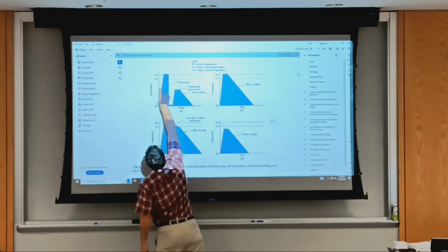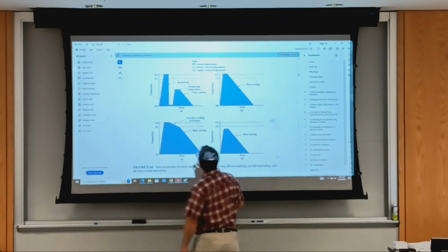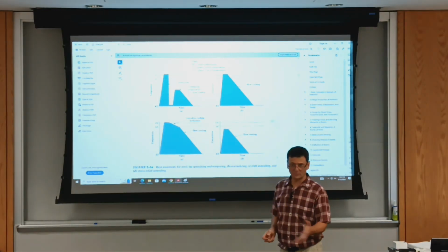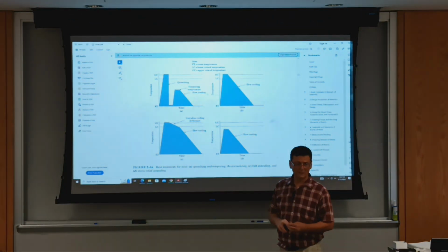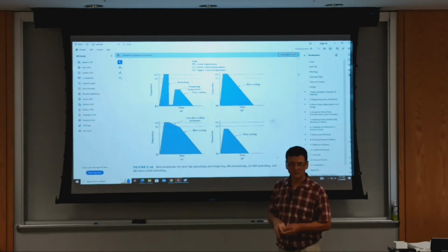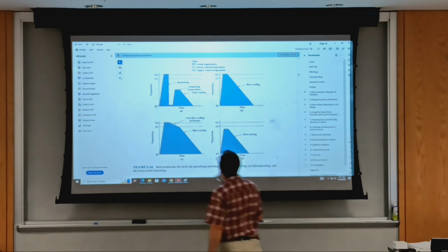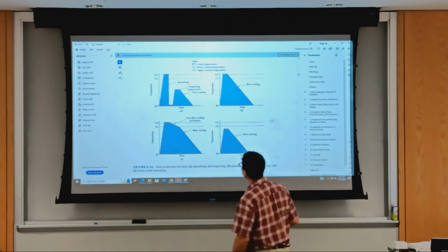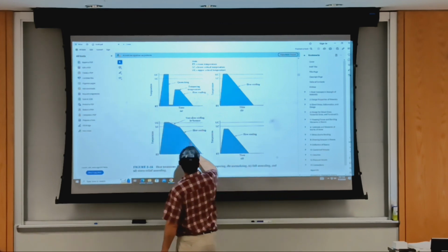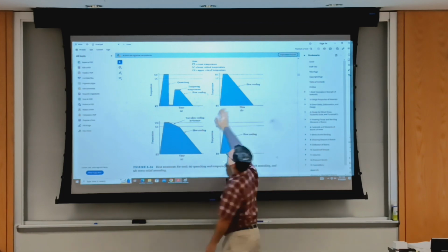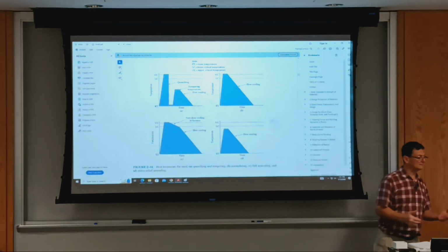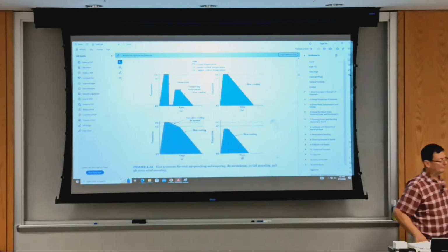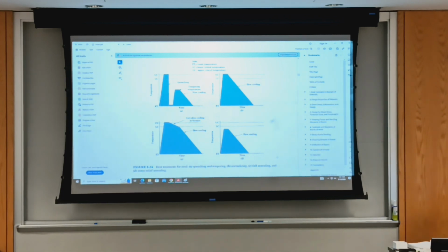You reheat it, but below the lower critical temperature, and you slowly cool it to undo some of the brittleness that comes with quenching. Have you been told of this, like martensite formation during quenching that is brittle but hard? And bainite is also a compound that happens through fast cooling. And then you have annealing, very slow cooling to improve machinability and formability, that is ductility. Quenching and tempering happens to improve hardness.